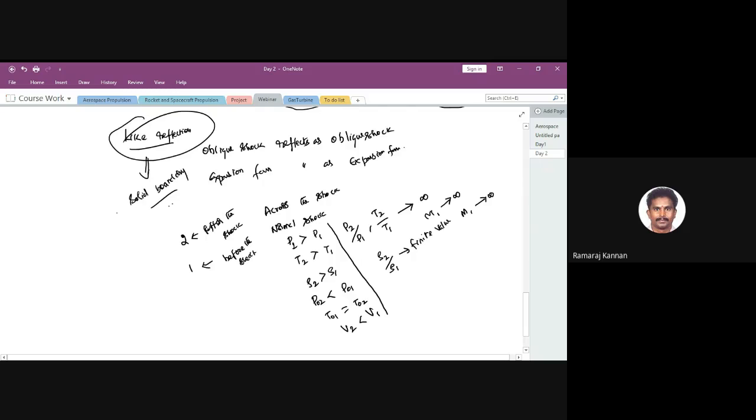And also, if they ask you what the governing equations for shock theory are, you can say: the continuity equation, momentum equation, energy equation, your entropy principle, and your perfect gas equation.